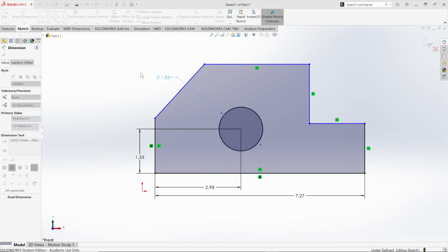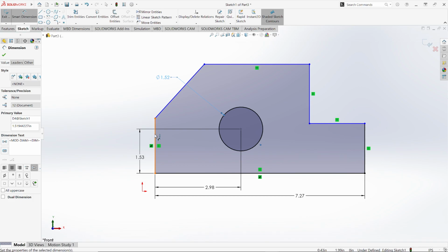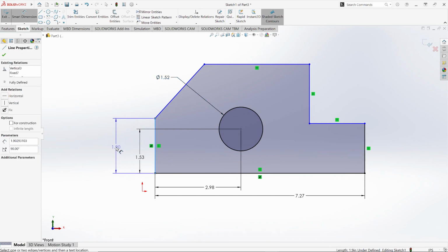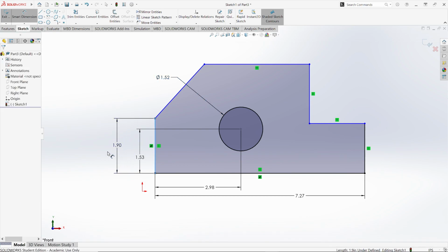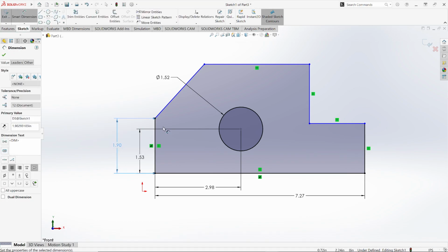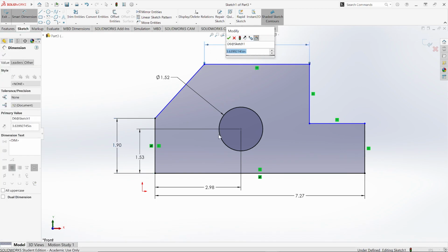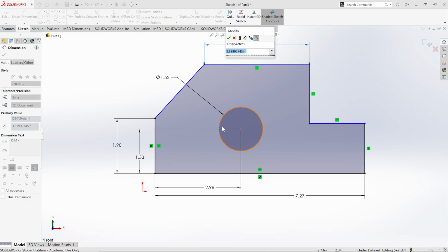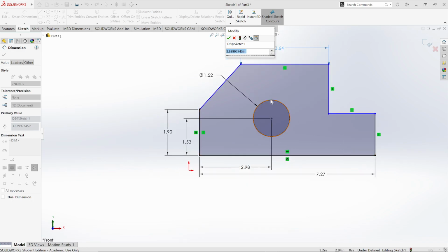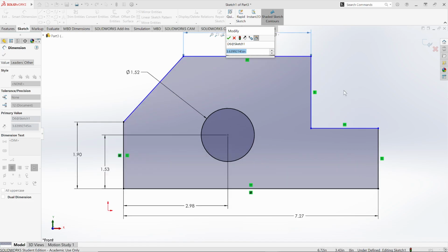You can also just hit the enter button. So when I click over here, instead of hitting the green check, I'll just hit the enter button, and I'll do this one up here, and you'll notice that everything dimensioned turns black. So the hole is black, this is black, but on the bottom here it still says it's underdefined. So I'm using the anchors to help me determine if this thing is dimensioned. As I create the dimensions from the datum, the element should turn black, verifying it.